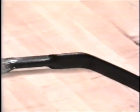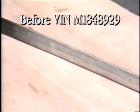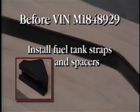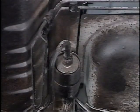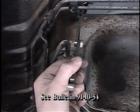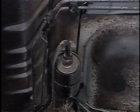If the car was built prior to the VIN breakpoint, support the tank and install current design fuel tank strap spacers and coated straps. On cars assembled after the VIN breakpoint, the groan condition is repaired by replacing only the fuel tank support straps and reusing the existing spacers. Ensure there is clearance of at least 4 millimeters between the fuel tank flange and the crossbar before torquing the strap retaining bolts.